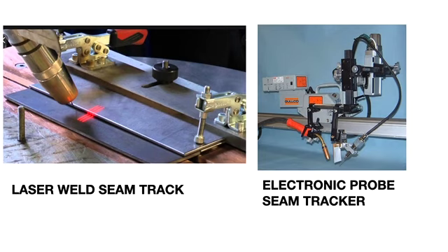Here the picture has been taken during one such process, where the movement is done initially with the laser assisted seam tracking, and then the trailing torch trails the laser, and then welding is performed. The adjustments of the arc length, the current, the voltage, everything is done automatically.